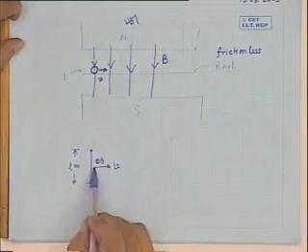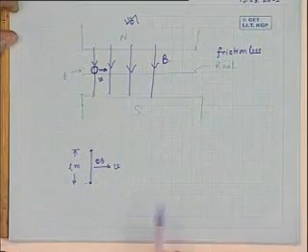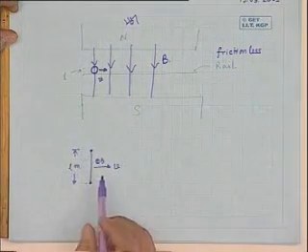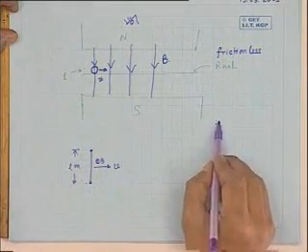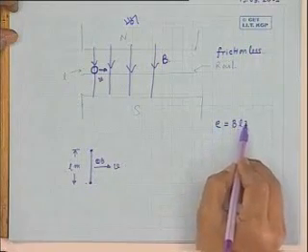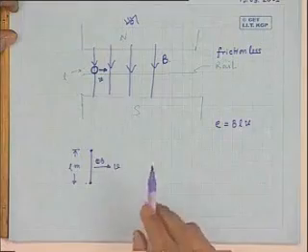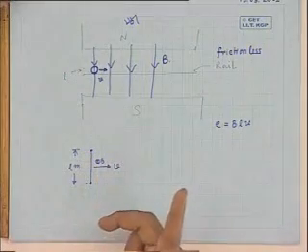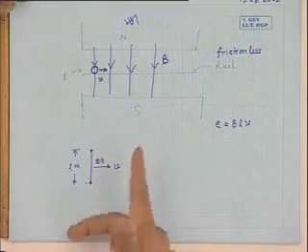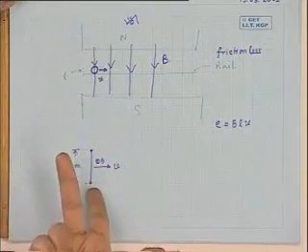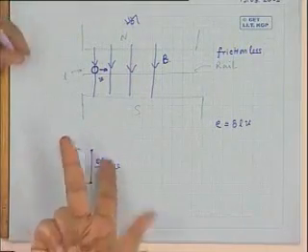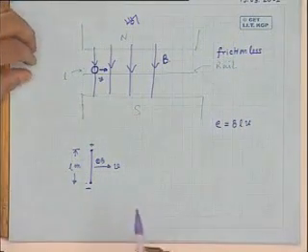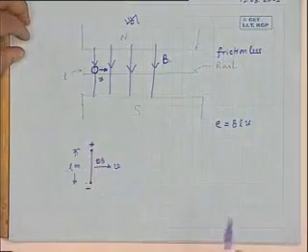Now, at any point of time, when it moves with this constant velocity V, there will be an induced voltage across the two ends of the conductor. The magnitude of that voltage will be how much? It will be B L into V, because they are in mutually perpendicular directions. Now, what will be the direction, the polarity, of that voltage? For that you have to apply the right hand rule. So the direction of B is like this, this is V, so this end will become plus and this end will become minus. Induced voltage polarity: plus, minus.